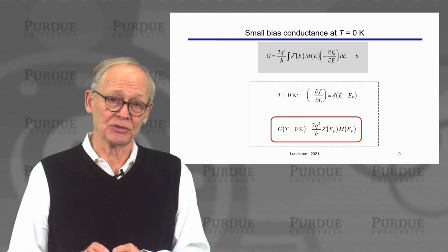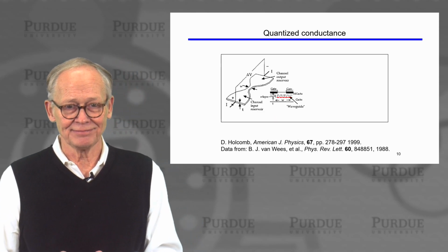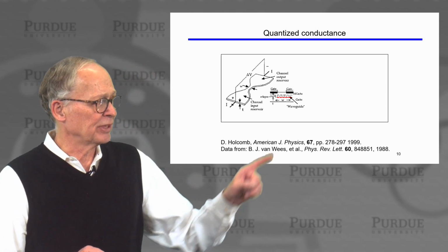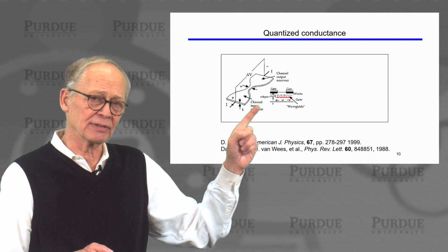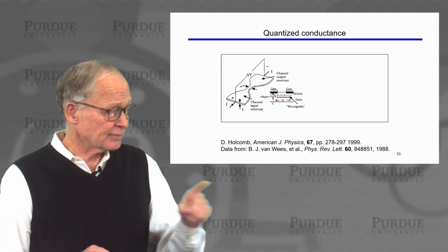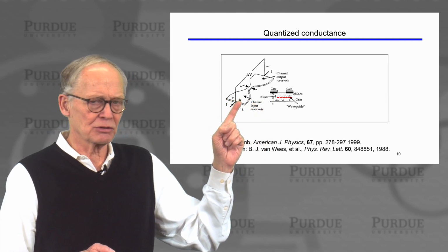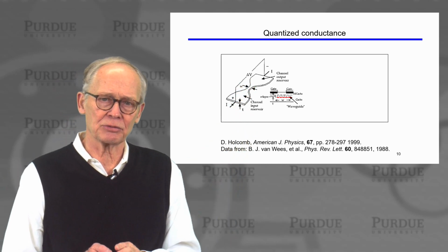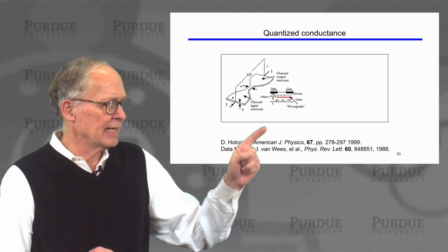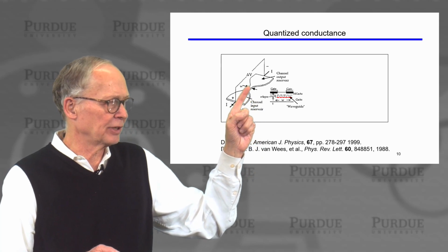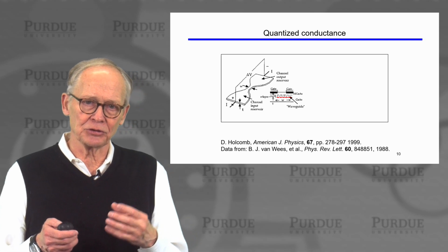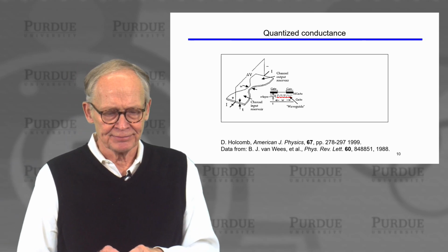Well, that's an important result, something that people discovered in the late 1980s, early 1990s, when they began doing experiments on very small nano devices. This is a very small two-dimensional resistor. It's very short between the two contacts, so the transmission is close to 1. And the width of this resistor can be controlled electrically by reverse-biased Schottky barriers.